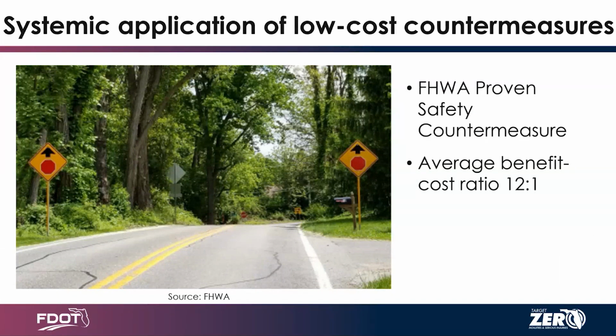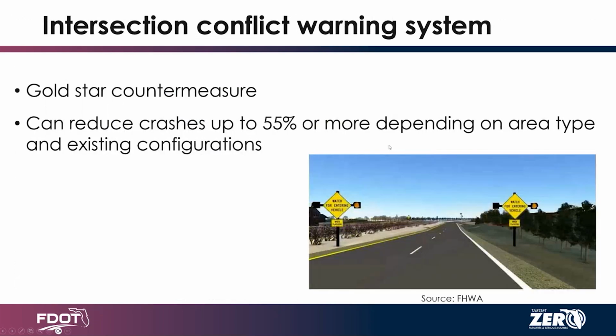In addition to the pavement markings and signage, there's something called a bright stick, which has potential to be put on signposts. So at night, the signpost really lights up. I can't remember if it's on the approved products list, the APL, but there are countermeasures out there that can improve nighttime visibility. This one is a relatively new countermeasure.